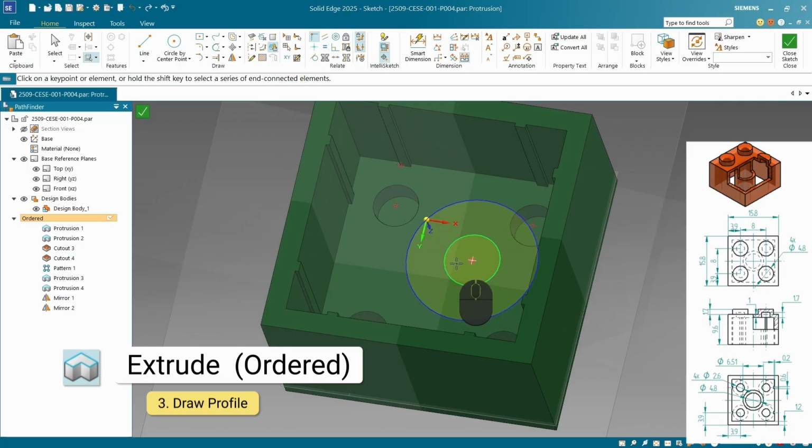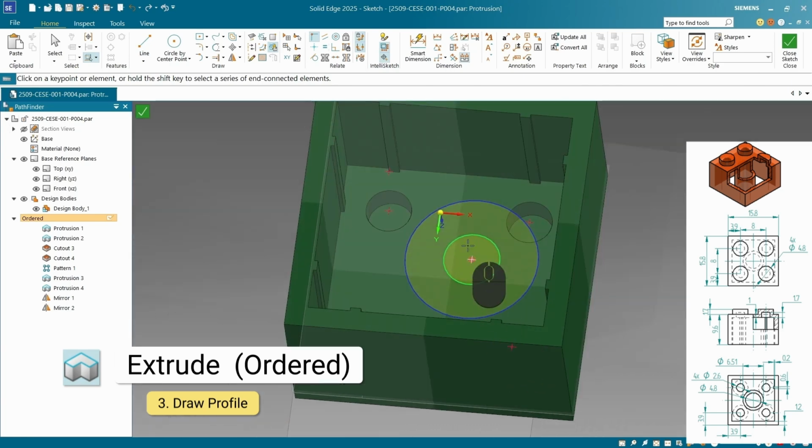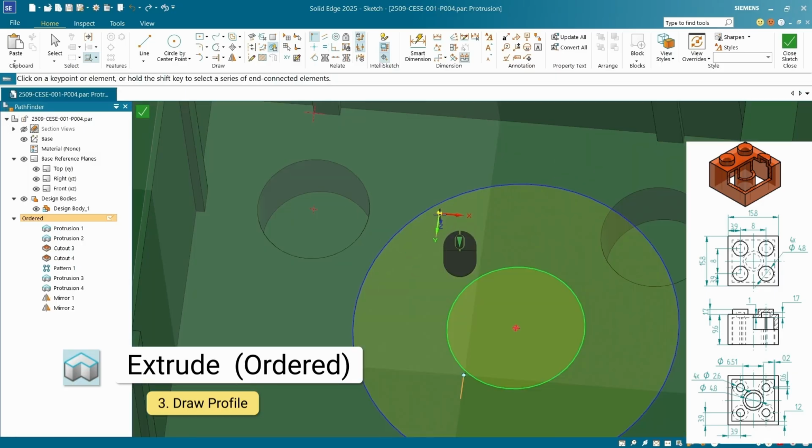What happens automatically when you're in a sketch, when you select something on a different plane, is it's projected to your sketch plane. So you can see as I'm hovering over the y-axis, you can see the orange line shown below it on my sketch plane. As I hover over the x-axis, there's an orange line shown on the sketch plane. And as I hover over the origin, there's a blue dot on our sketch plane. So that's what I'm going to click on.